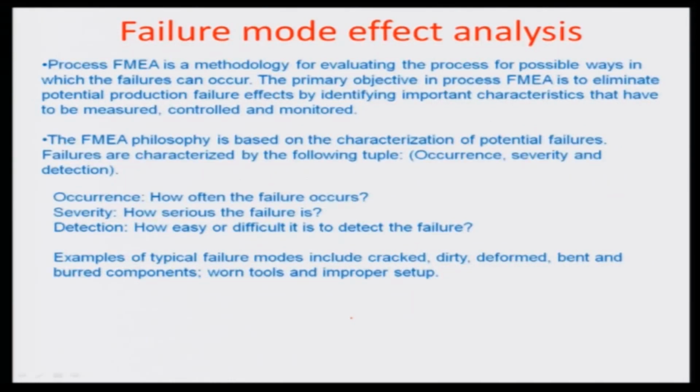So the methodology that is typically used for the process FMEA is to, again, the philosophy is really the characterization of the various potential failures and its causes of a particular system. Okay, and the failures can further be characterized by three important things. One is the occurrence, that means how often a particular failure mode occurs.